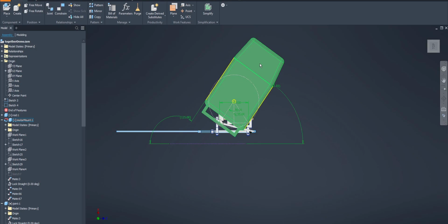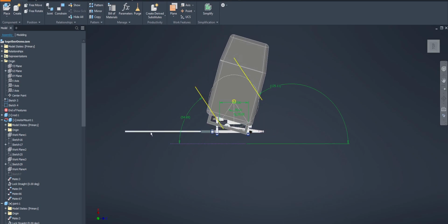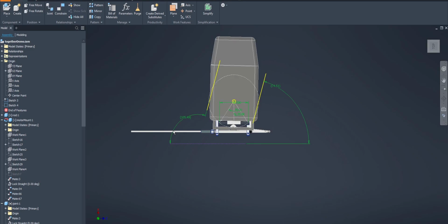And what's more is that the center line of the motor is sitting at that 35-degree angle, and when I move it the other direction, the center line of the motor is sitting at the other 35-degree angle, which tells me that I've got a full 70 degrees of sweep with this configuration. So that's how I've figured out how to get this geometry to work and calculate everything that's required.